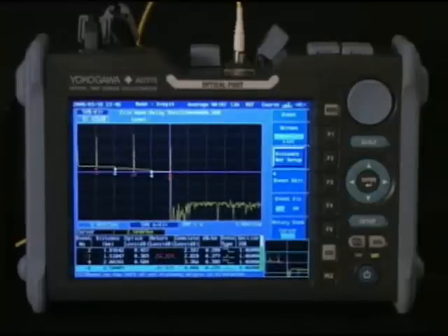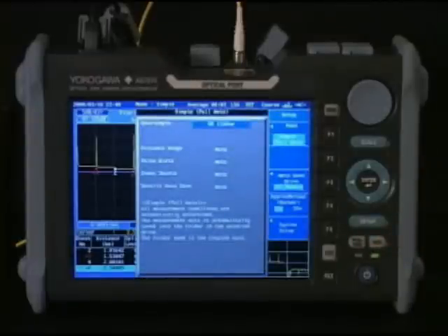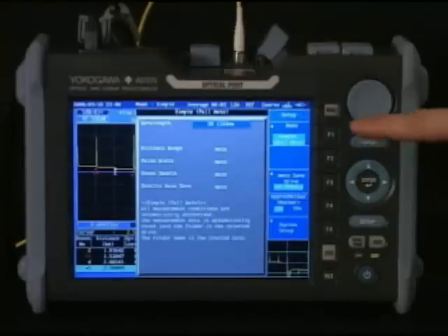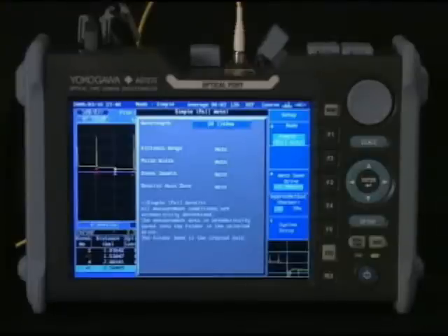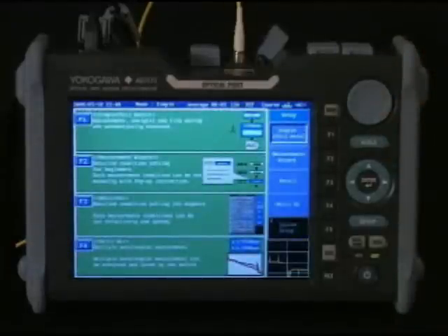For more advanced controls of the OTDR test, just select the Setup key. The AQ7275 will normally show Simple, also known as Full Auto, for the setup mode. However, there are 3 other modes besides Simple. Selecting the F1 mode key will show you those options.